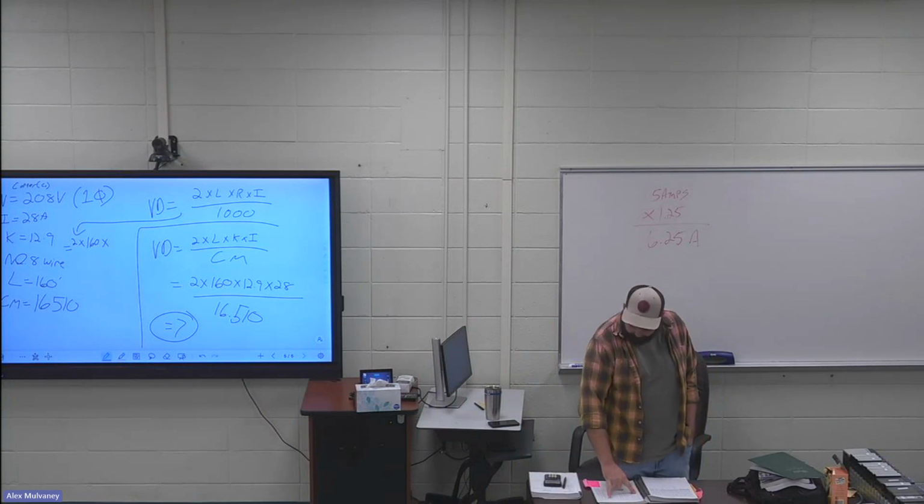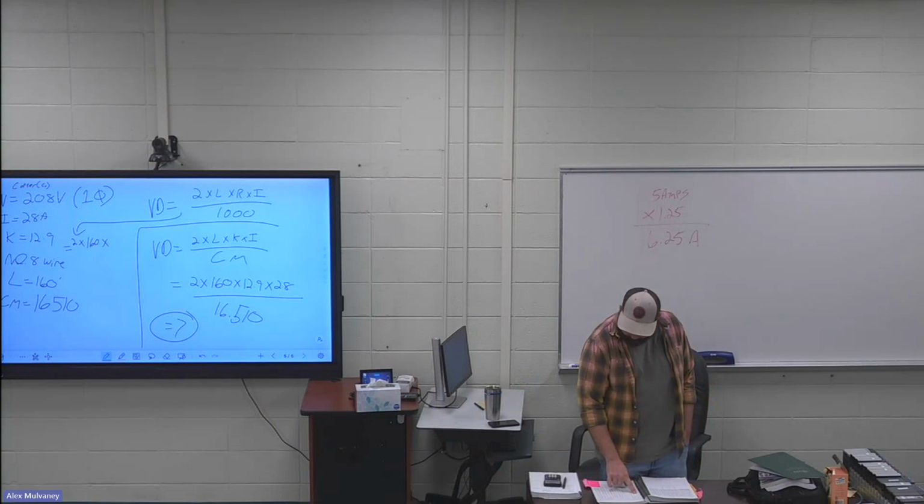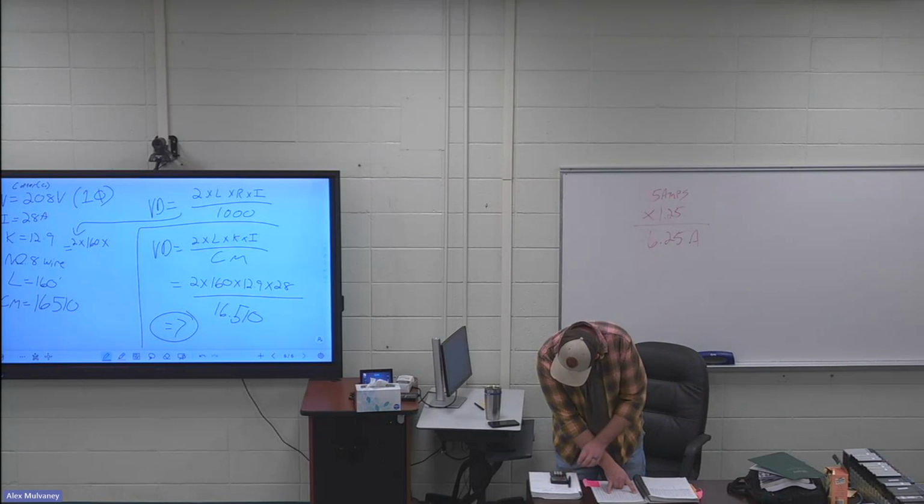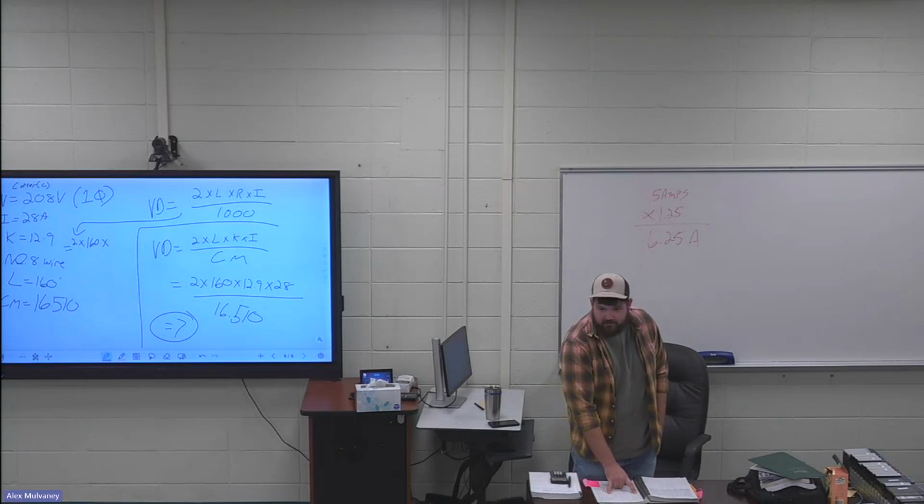Then I go over, and everybody look up closer to the top, everybody see copper? And then what are we using, kilometers or feet? Feet. And if it's not noted, do you do uncoated or coated? Uncoated. Unless it's marked, you do uncoated. So we are in the copper, uncoated, ohms per kilofoot column. 0.778. Does everybody see that?